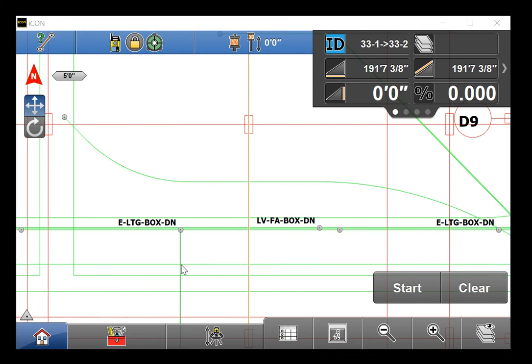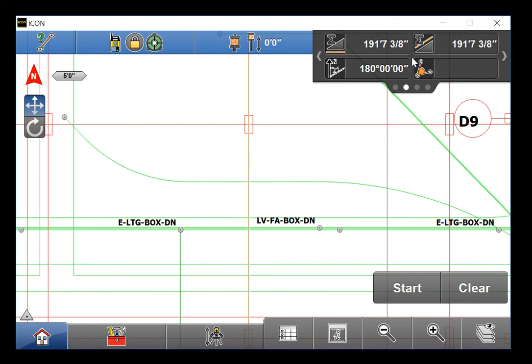Turning the prompt page displays more information. The upper left box contains the sum of the lengths of the lines selected measured with horizontal distances. The upper right box contains the sum of the lengths of the lines selected measured with slope distances if the lines have changes in elevation. The symbol next to the triangle means sum.